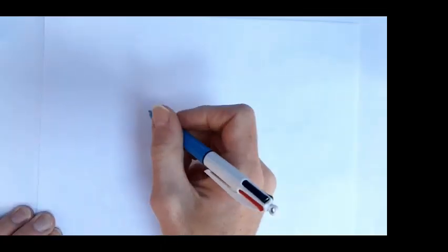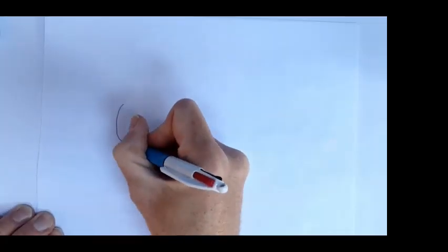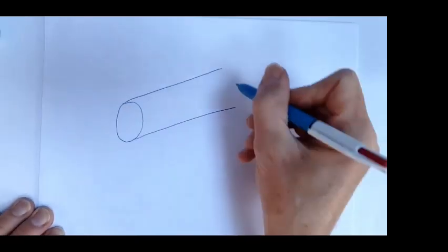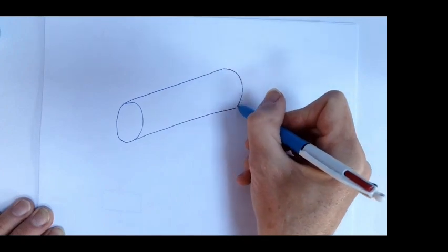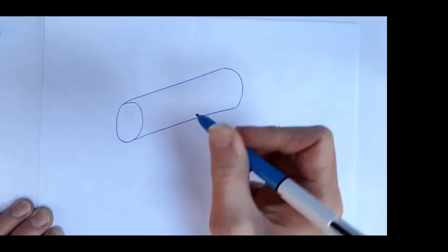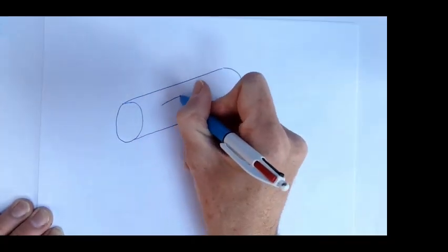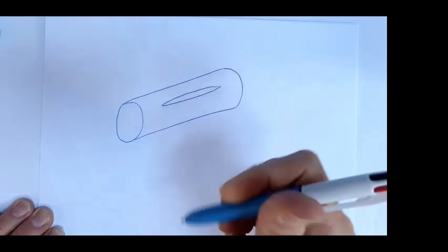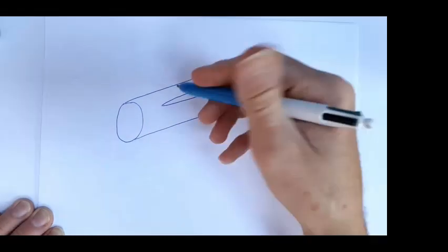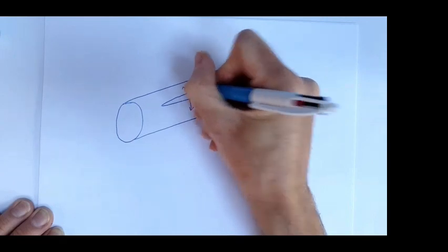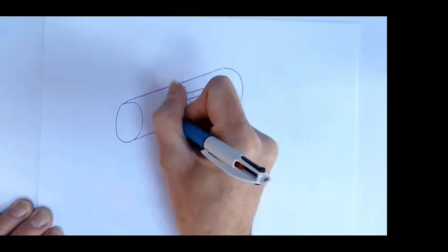Well, they split longitudinally due to the fact that the hoop stresses are greater. So let's consider a cylinder, a sausage. We're cooking that, so we're putting some pressure on the inside. It's gases expanding internally, and if we don't pierce those sausages, what do they do? They split in this direction. Now, the reason that they split in that direction is that the stresses in this direction are twice as big as the stresses in this direction.